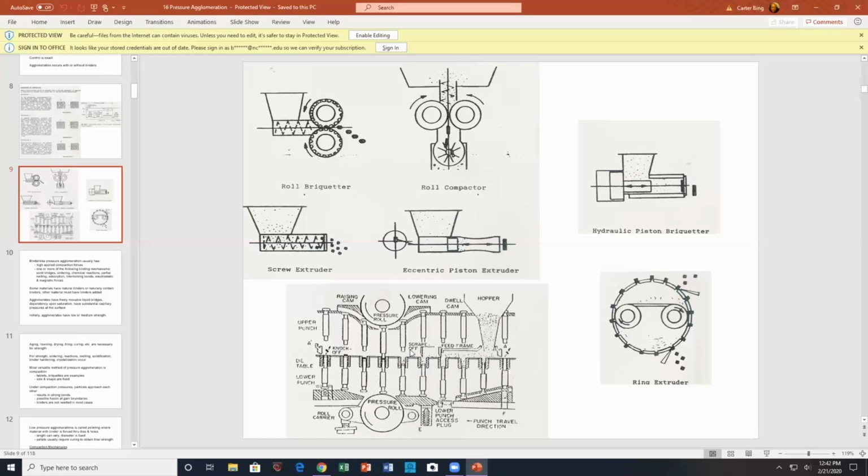Now, you may think those ribs are there for reinforcement, but actually those ribs are there so that as you pour water or liquid down the funnel, the air, or the gas inside the bottle, can escape. The funnel sits in the hole of the jug with these ribs along the perimeter, which leaves a little air gap or air clearance in there. It lets the air out